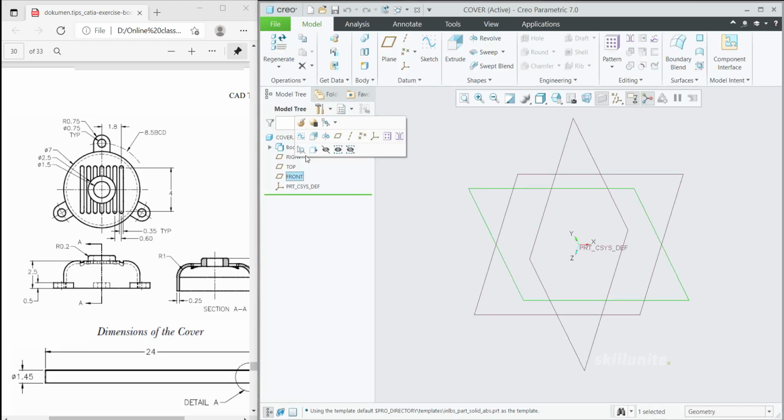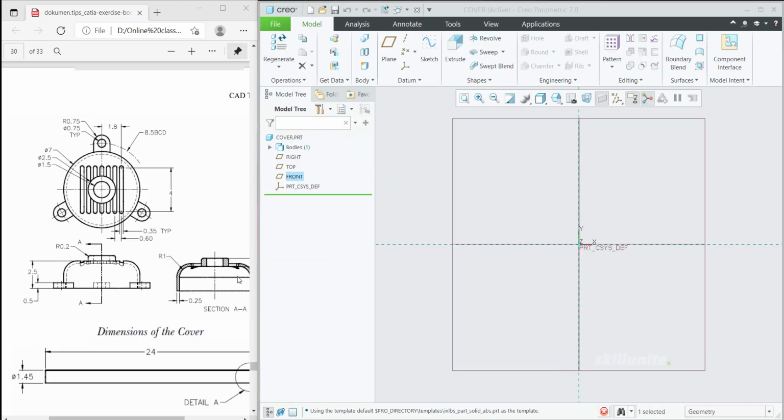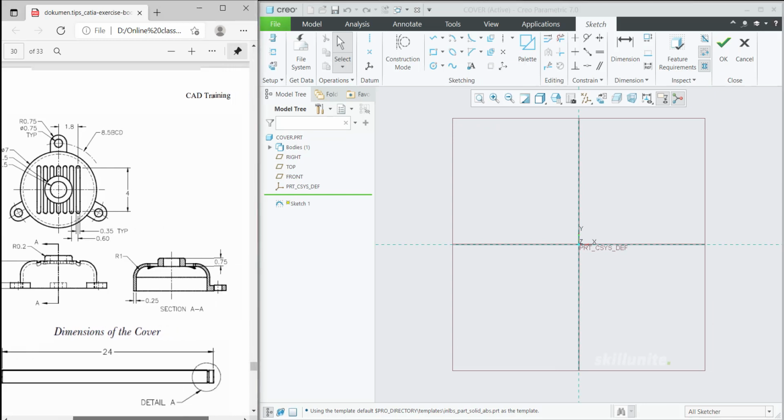First of all we are going to choose a plane and then we are going to make our sketches. Either you can use the revolve option, or you can use extrusion and then use the shell option. Anything is fine. So now in this session we are going to use extrusion. Let me choose from here and then make it straight. First give the dimension for one, then only we can get to know what it is exactly.